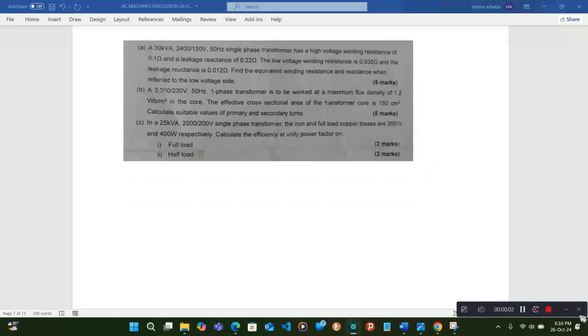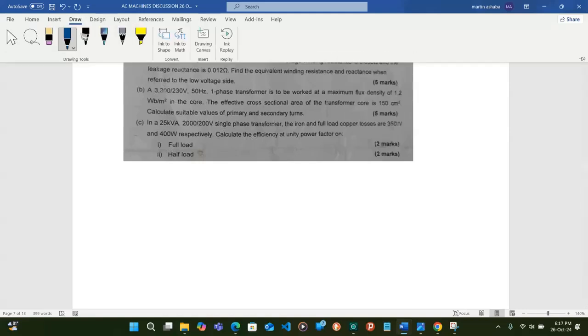We have part A, which says a 30 kVA, 2400/120 volts, 50 Hz single phase transformer has a high voltage winding resistance of 0.1 ohm and a leakage reactance of 0.22 ohms. The low voltage winding resistance...